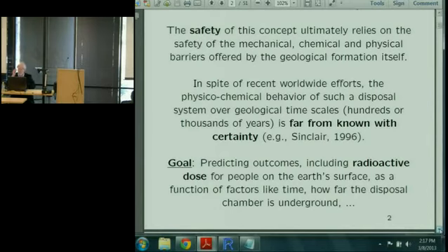Well, what could happen? Maybe you were wrong about the geology, and maybe 800 years from now there is a big earthquake right there. Then the containment vessel is going to fracture, and radioactivity is going to start to seep out, and the way it'll do it is that the radionuclides, as they're called, will bind with water molecules, and they will diffuse in cracks in the rock. And so you can use applied mathematical modeling, fluid dynamics based on diffusion processes, to predict how fast the radionuclides would migrate from underground to the surface, or at least close enough to the surface for it to contaminate drinking water.